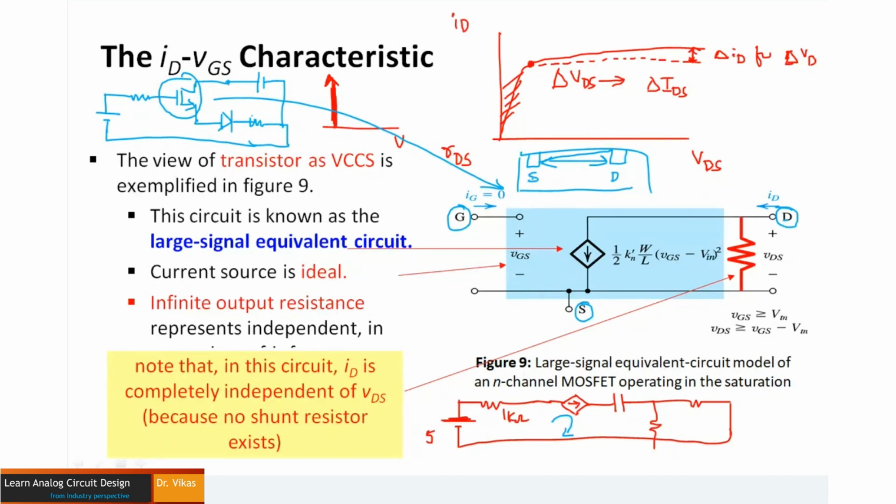That's why between drain and source the current of this much nature is flowing, and that current is a dependent current with a small resistance offered in the saturation region represented by the small r, and with a gate terminal connected like this. So this is basically a model of a particular MOSFET, which we call a large signal equivalent model. Now here, whenever I want to solve any network based question, I can replace this MOSFET with this particular model, which can be seen over here.